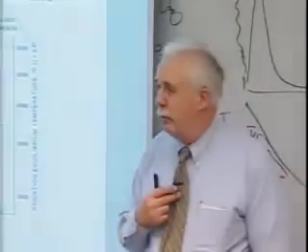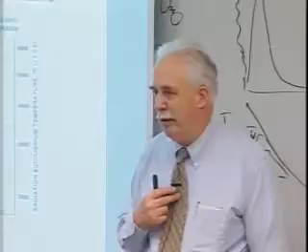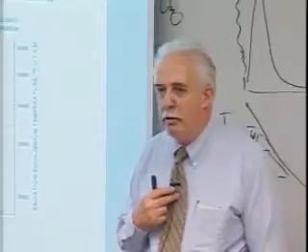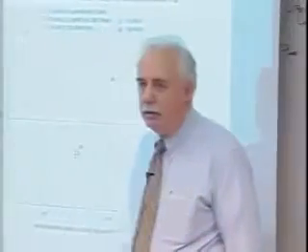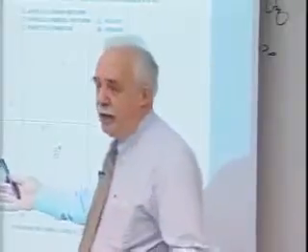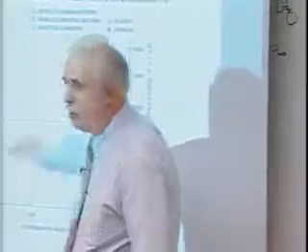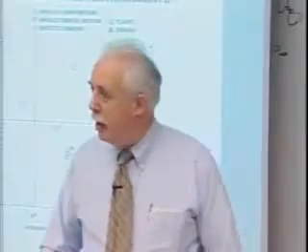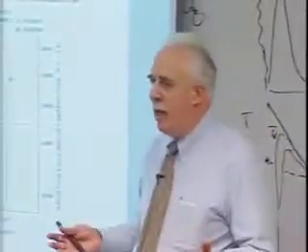Boy, I sure don't want to put too low a heating rate in. I don't want to be the cause of a failure. So I think the heating rate's going to be right here or whatever. Well, I don't have that level of confidence. I've got some uncertainty. So I'll put 10 or 20% at least on my heating, right? The ablator guy, he's testing in arc jets, and he does exactly the same thing.